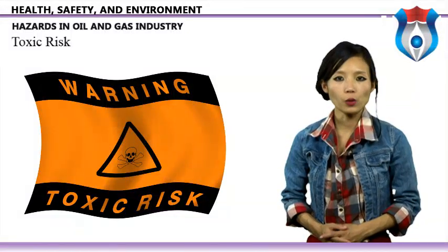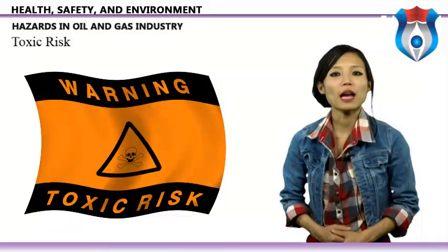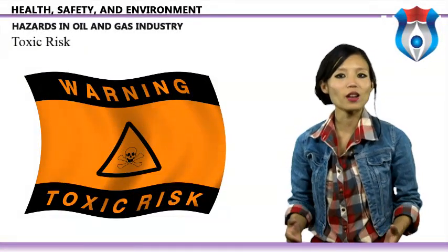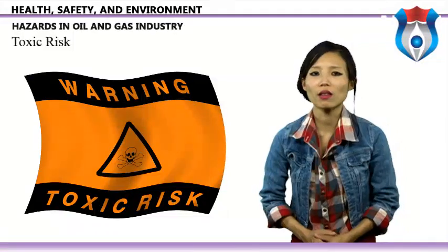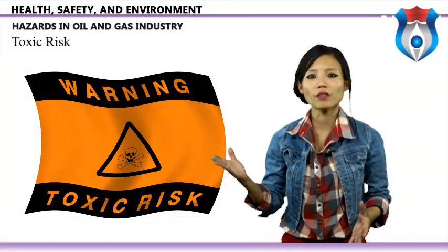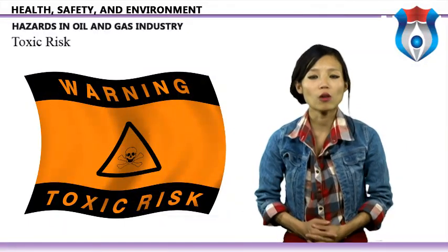Given that 10,000 ppm is equivalent to 1% volume of any space, it can be seen that an extremely low concentration of some toxic gases can present a hazard to health. It is worth noting that most flammable gas hazards occur when the concentration of gases or vapors exceeds 10,000 ppm, 1% volume in air or higher.